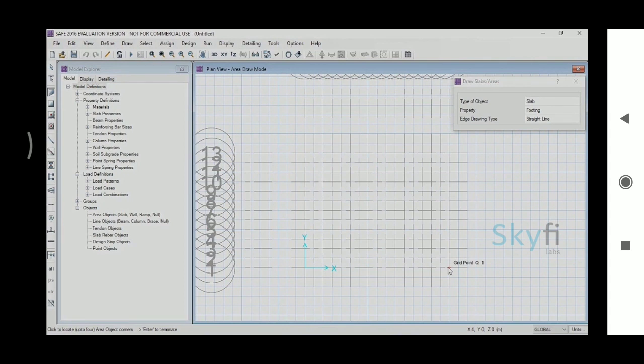Thus, we have to leave half a meter both from top and bottom, while drawing the left edge. Therefore, the third corner of the trapezoid is 4 meters to the left, and 0.5 meter above. So select the next point accordingly, then click on the next point, 2 meters above. After that, come back to the first point, and click on it, to close the figure.